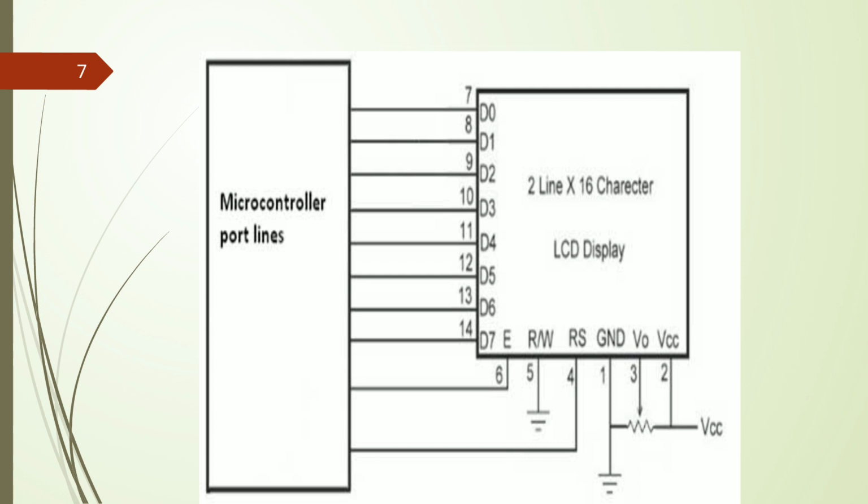So by making a high to low pulse for some time interval, it should allow writing or getting the access of the LCD with the microcontroller. So the EN or E pin is used for enabling the LCD to access either command mode or data mode. For each instruction, it should be high for a particular time interval, and again it should be applied as a low signal or connected to low signal. So these are the three most important control signals.